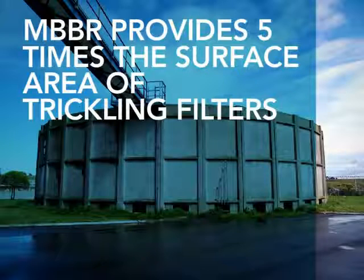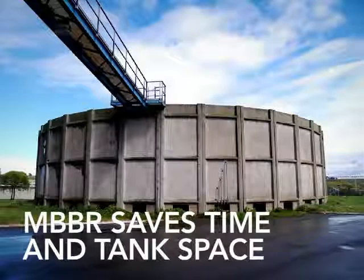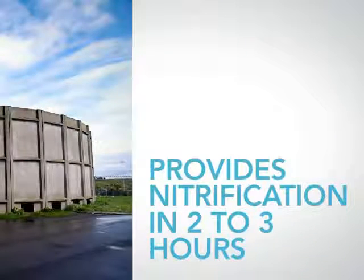When compared to an activated sludge extended air process, MBBR saves time as well as tank space. Whereas activated sludge is designed for 12 to 24 hours of hydraulic retention time, MBBR needs only 2 to 3 hours to achieve the same level of nitrification, using a quarter or less of the tank volume.